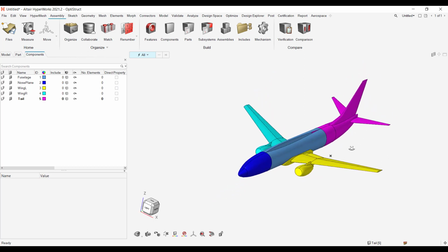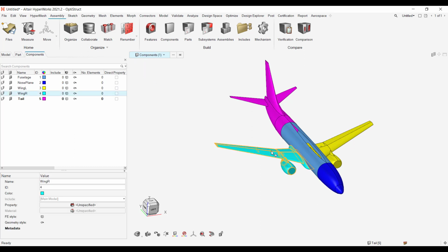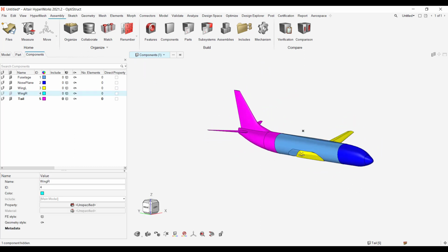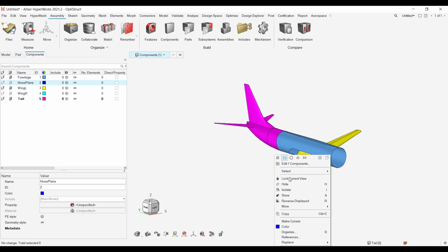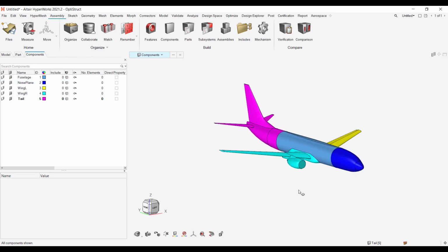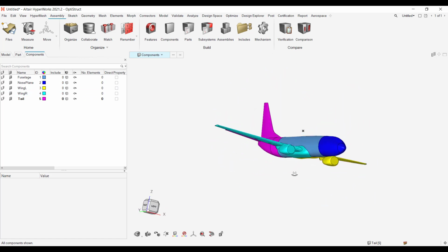All right. So that's kind of some show and hide, right? So once again, just change my idle selection instead of all. I'm just going to change it to components and hit H on my keyboard to hide. Select something, hit H to hide. A is show, so show all. I can hit A on my keyboard to show all. Okay, perfect. So that's some selection.